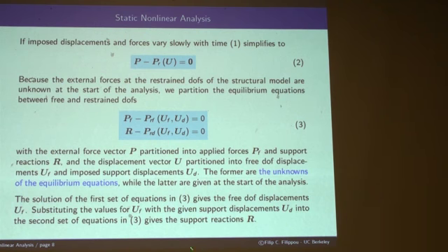All right. So, because the external forces at the restrained DOFs, in other words, DOFs whose displacement values are known, are unknown at the start of the analysis, we partition this set of equations into equations at the free DOFs and equations at the restrained DOFs.